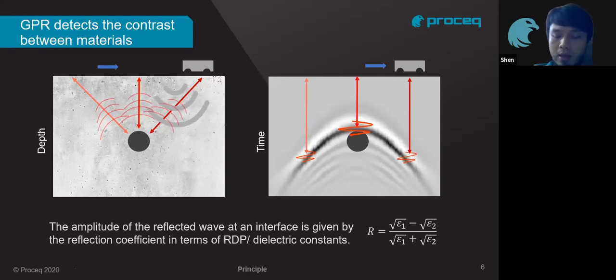When it starts to capture data at the first location, the radar that travels to the specimen takes a longer time to detect the signal, right? So it comes off as a longer time of flight duration. In the actual data collected on the right side, you will see a hyperbola kind of imaging that actually represents, for example, a rebar.